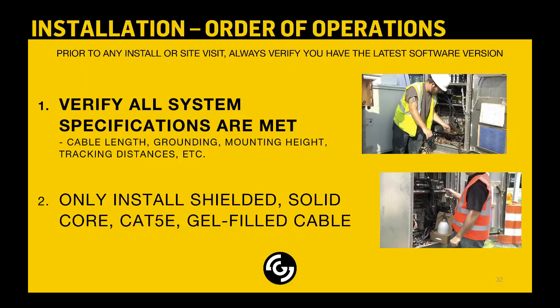The gel-filled cable, you know, this is important too because it's going to mitigate and eliminate, hopefully, any water ingress or moisture buildup inside the cable. You know, you never want to use just regular Cat5 cable. It needs to be Cat5e gel-filled, the burial grade type.